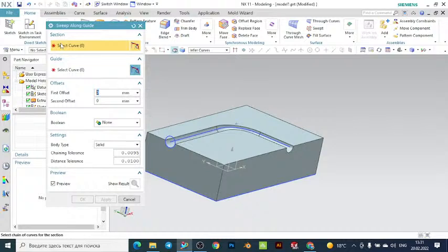So when you have complex shapes, it is not possible to use this function. It is mostly used for creating tubes with a single cross section and a single guide curve. You can also use the offset function to create offset values on the sweep volume. Also you have seen the Boolean with Unite, Subtract, and Intersection.